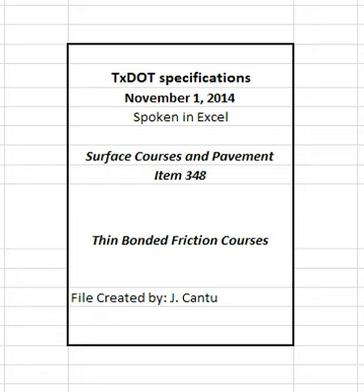Remove substantially all materials before use that are not part of the shingle, such as wood, paper, metal, plastic, and felt paper. Determine the deleterious content of RAS material for mixture design purposes in accordance with Tex-217-F, Part 3. Do not use RAS if deleterious materials are more than 0.5% of the stockpiled RAS unless otherwise approved. Submit a sample for approval before submitting the mixture design. The department will perform the testing for deleterious material of RAS to determine specification compliance.